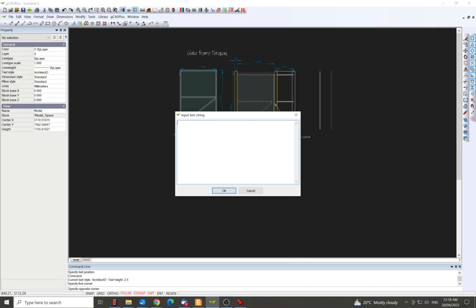So basically details, gate frame, we'll say, shall be made from galvanized tube 30 by 30 powder coated in night sky.